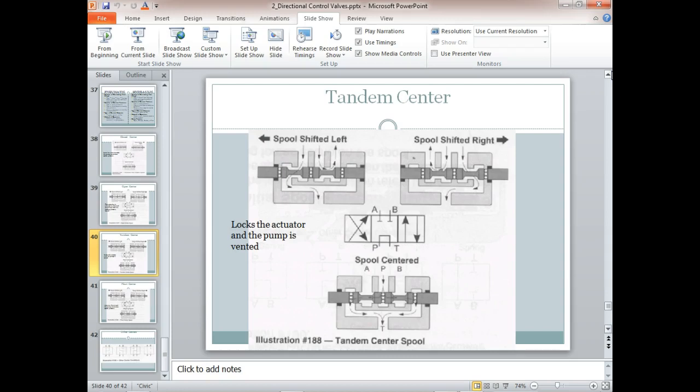So we have dual piston cylinders, double rod cylinders, and rodless cylinders, which the book doesn't cover. If you're going to run into rodless cylinders, we showed y'all some over there, and we talked about those a little bit. We have telescoping cylinders, which is basically what they use on dump trucks and stuff like that. Have y'all seen those things? You know what I'm talking about?